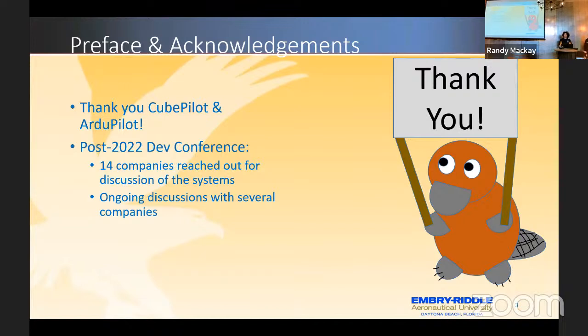We need a low latency data link, so those 3 flight computers, or 4 if you put in, can actually share the synchronization data between them, and we can keep them synchronized so we don't end up with a lane switch followed by an aircraft that's flying to waypoint 3, while the other suddenly tries to fly back and go to waypoint 7. Exactly. I'm not quite sure what links we've got available at hardware level for these nodes to talk to each other, sending data across for the critical process.